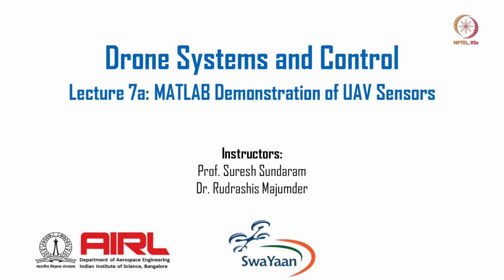Now if you are looking at simulating these sensors, we need to understand how you can add the sensor in the simulation world. We also talked about how we can create the mathematical model, and how we can simulate the drone in MATLAB, the 6 degree of freedom model we talked about. Now it is very important how we add the sensors to this model and add practical noise to these sensors, so that the model you have is as close as possible to the real world.